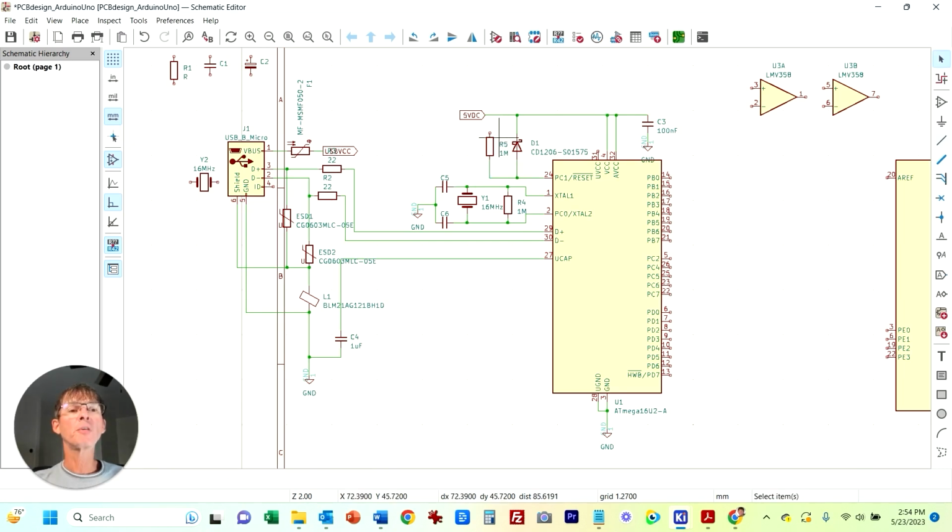So a pull-up resistor that you'll hear commonly is just a resistor that's tied between whatever the main node is that you're trying to pull up, in this case the reset, and then the positive supply. And it's called a pull-up resistor because as long as there's nothing pulling this down, like say a switch, or say the microcontroller, if this was an output, and it was trying to put this low, then if that's not there, this resistor will pull this net up high.